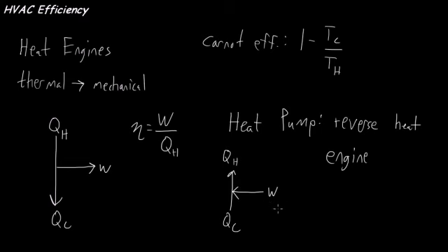Heat pumps basically work using a refrigeration cycle, which you probably learned about in your HVAC class. So we supply mechanical work via a compressor, and we can transport heat from where it's colder to where it's warmer, which is inside. So let's indicate that's the room.